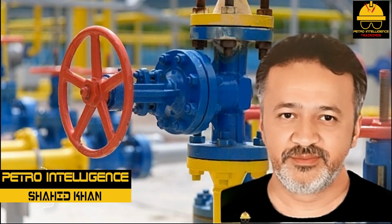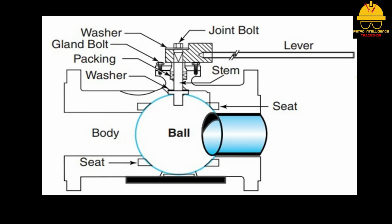Ball valves. Ball valves take their name from the ball-shaped, movable element in the center of the valve as shown in picture. Unlike the gate and globe valves, a ball valve does not lift the flow control device out of the process stream. Instead, the hollow ball rotates into the open or closed position. Ball valves provide very little restriction to flow and can be fully opened with a quarter turn on the valve